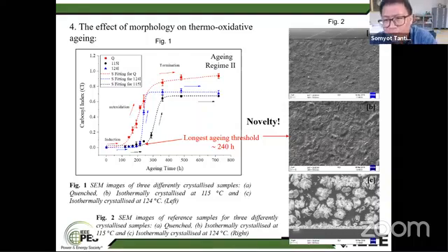So you can see the white lines here in the figures. This is a lamellar structure, or the crystal structure of the polyethylene chain, that's filling the space throughout the bulk of insulation. And then in figure C, this is polyethylene produced with the crystallization process at 124 degrees Celsius for 4 hours. The crystal will be bigger than the others, about 20 microns. And then you could see the black space surrounding the white crystals here. This is amorphous, containing low polymer chains.